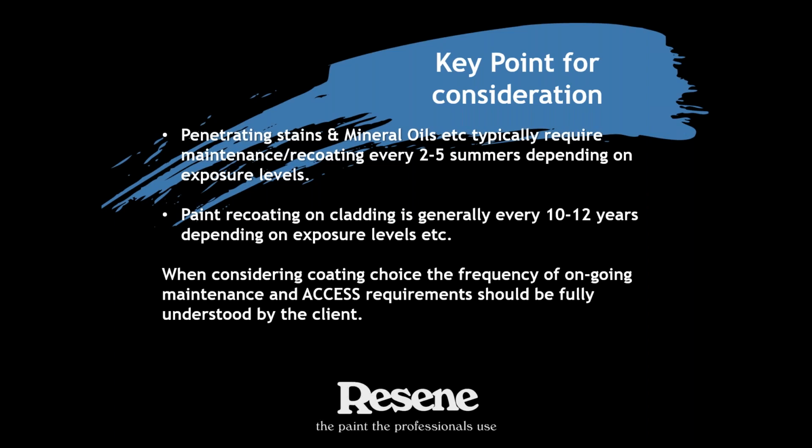Paint coatings, and we haven't talked about those today, but they are typically on cladding systems every 10 to 12 years, depending on the exposure levels. So there's quite a difference in the repainting or restaining periods. And the one thing that we feel sometimes gets missed out is, again, it's about expectation and understanding by yourselves and your clients, is the access requirements to do that.